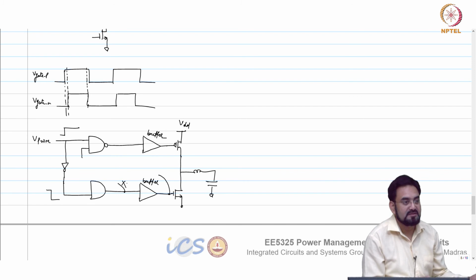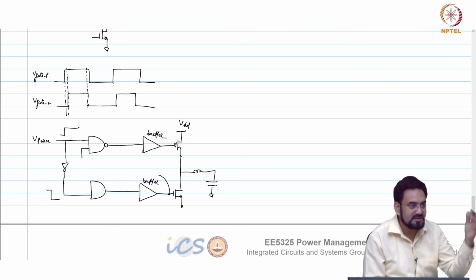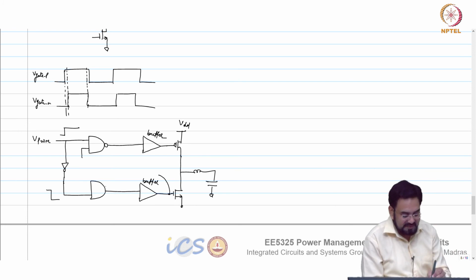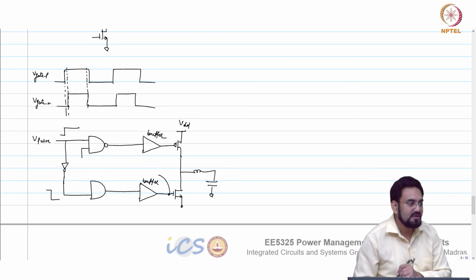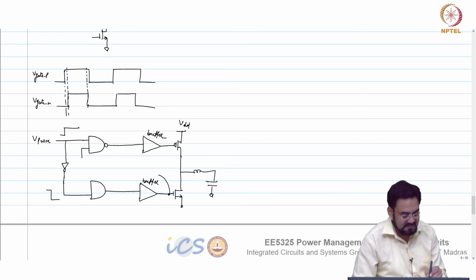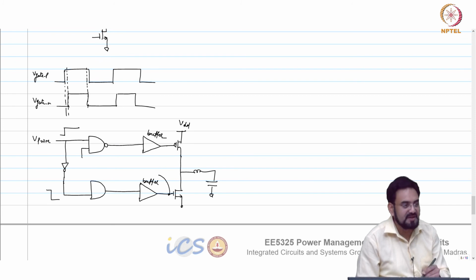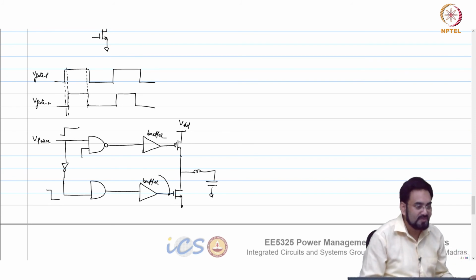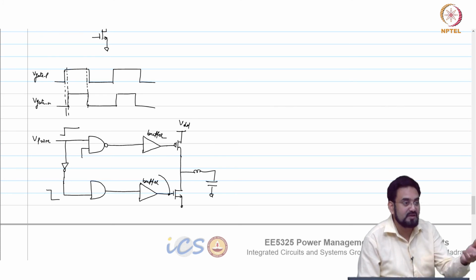This is wrong, okay, but if you look at any digital logic book or anything, they might be taking feedback from anywhere, because they are not driving such a huge gate. So the rise and fall time and delays looking at this gate node will be relatively the same compared to the previous stages. In that case, you can take the feedback before this buffer also, but here you know that the rise time and fall time itself is 1 nanosecond.